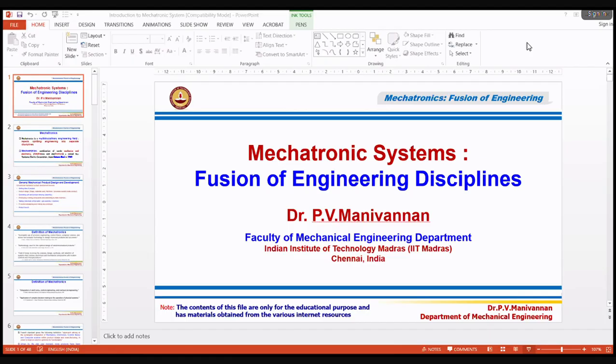to make the individual parts, called prototyping. You make individual components, then you will assemble them. This product is called a prototype. It is not going to be used immediately in the actual machine or actual product, because you are trying to make a new product. So individual components are assembled, a subsystem or assembly is made, and that will go under testing. Many times generally they will test the individual components first.